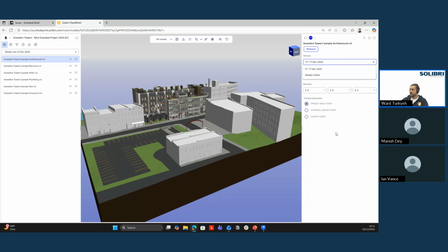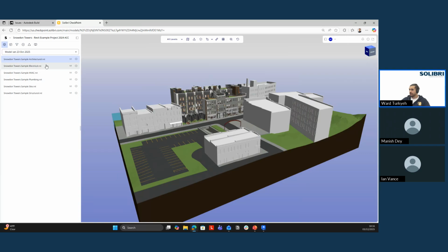This allows me to get the information in real time, eliminating the manual work that required us to download the file, re-uploading it, and so on. We have a direct connection, so we're retrieving the information in real time. And right now, I'm loading only Revit files, but you can also add IFC. You can combine them both, and then you can federate them and show them in the 3D viewer. And that's for the models.